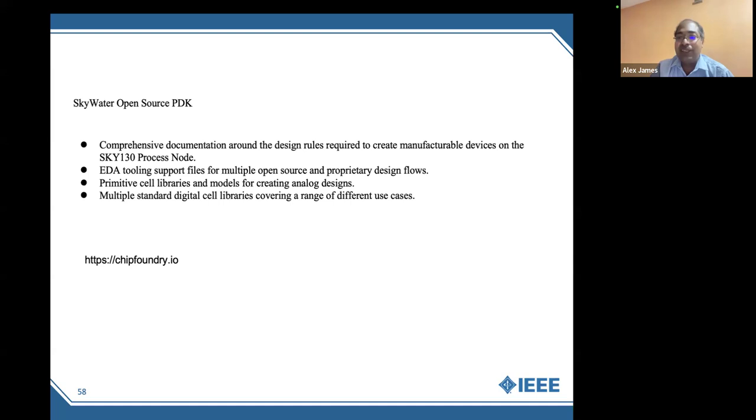Many a times in digital, this is not a huge problem because you have the behavioral code, you can work with that, and the synthesis and all those things are fairly robust and mature. Whereas with analog, if you are not sure what you're doing, in some cases you might have certain issues while you finally tape out and fabricate. When the chip comes back, then you see all sorts of different issues coming out. So you just need to have a sense of what kind of circuit, what frequency range you're going to work on.